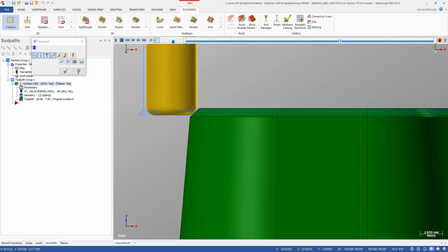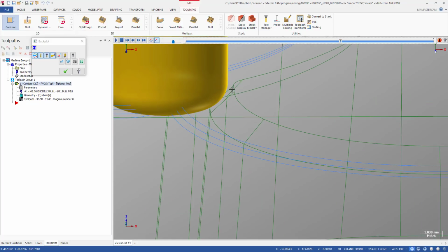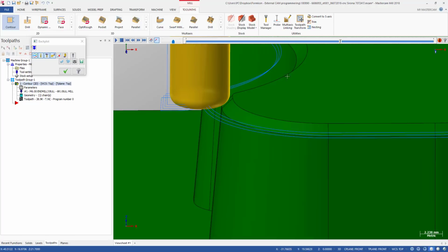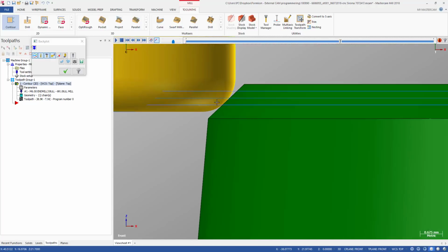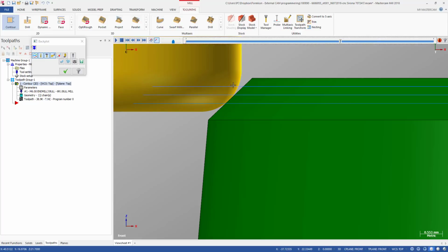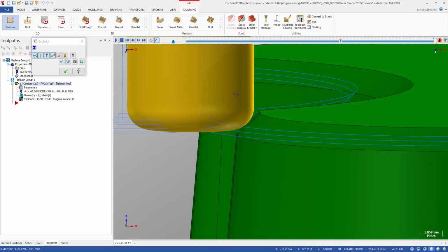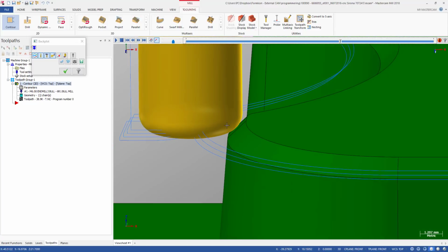We just select the top edge of the taper wall, and we input the value of the angle, and when we select a bore mill, you can see Mastercam automatically calculates the contact point of the tool and the surface. So this is really amazing.